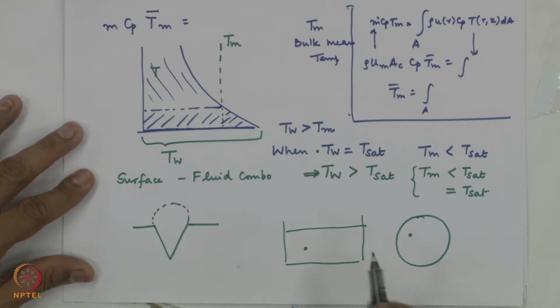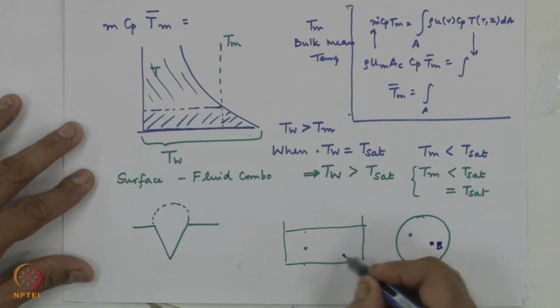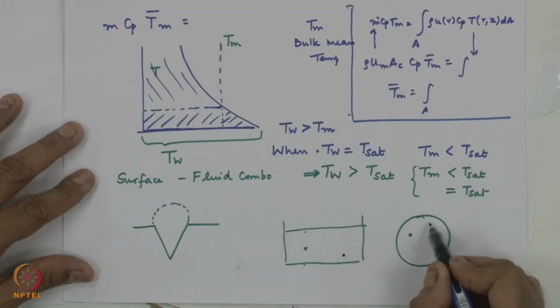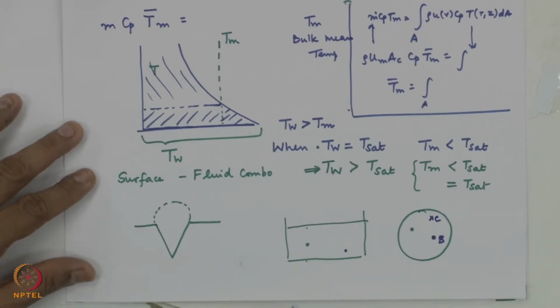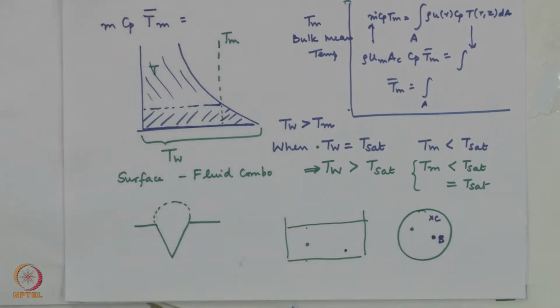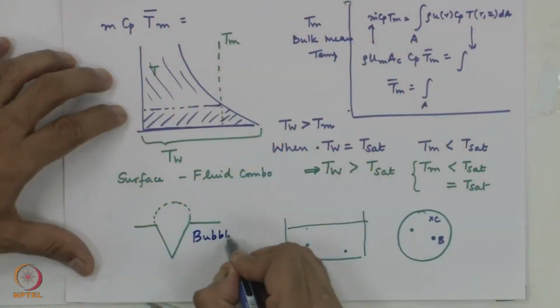After some time, you do not change the flame, the bubble will come out from the same spot, move up to the top and then collapse. Simultaneously, at another point B, a bubble would be generated, that would come, do the same thing. Later on at time T3, this is a point C where a bubble would be formed. This process of bubbles being formed at specific sites, all of us have observed this, at specific different times, is a result of the fact that boiling is a very local phenomenon and it is governed by the process of bubble nucleation, meaning this is the birth of the bubble.